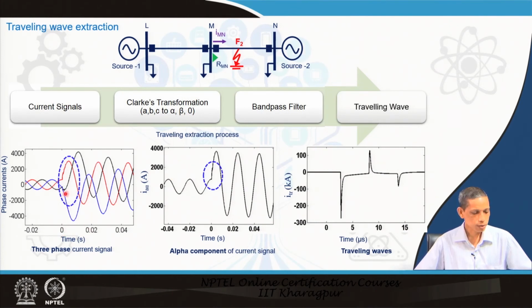So the phenomena associated with the travelling wave are in this portion, the small noisy portions, and that reveals all the perspective. Therefore, our sampling rate requirement is very high, and there is also the scope for a fast relay decision.